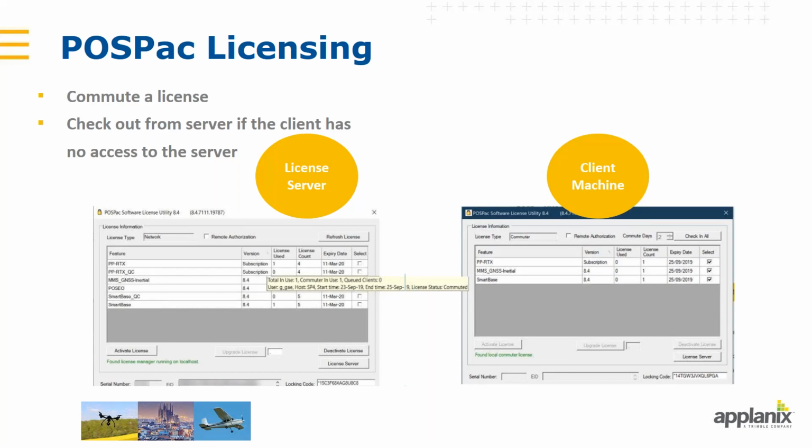You can select, as I said, the license server and license features, and specify the time. For example, in this case, the license features were checked out for 2 days. And then you can leave the company's network, when you are working remotely for example, without access to the license server. On the license server itself, the checked out license features are shown as in use. So the license is used and it's not available anymore for the time when this is checked out. After the time, the license features are checked in automatically.